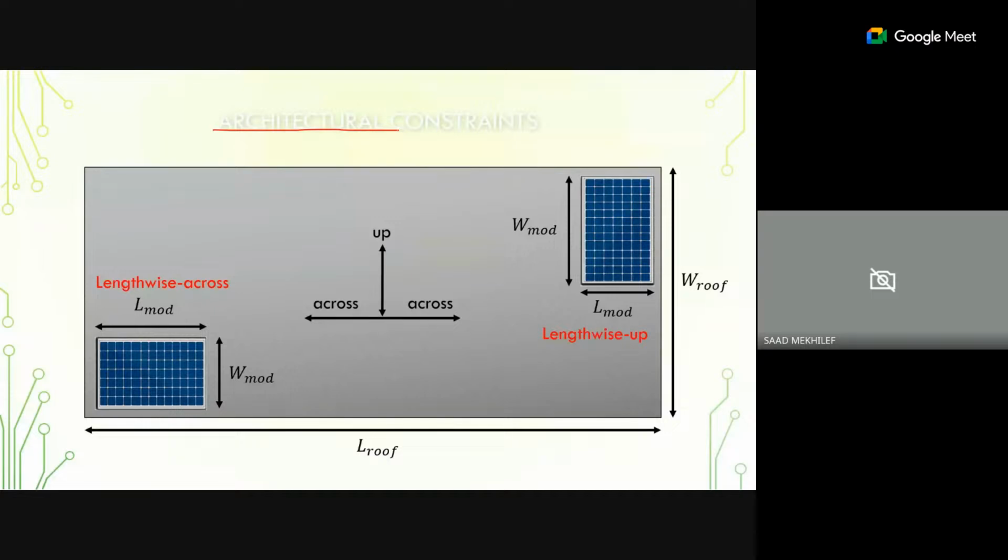So you have the PV panel, and that's why the selection comes. What types of PV panels should we select? Okay, because you may find 1 meter square gives you 200 watts, and then you may have another 1 meter square that gives you 500 watts. If you have a space limitation, you should go for the 500 watt. Yes, it is expensive. Maybe the price is double, maybe more. Okay, but this is necessary. This is to select the right size.